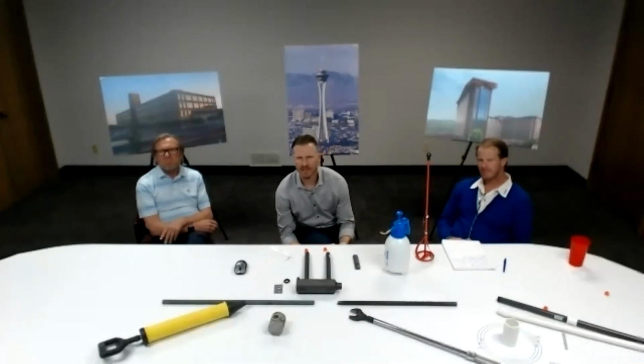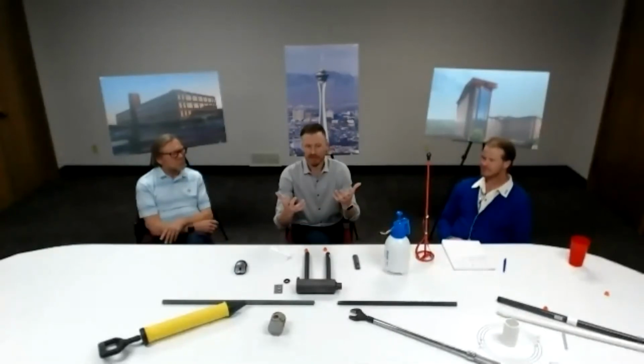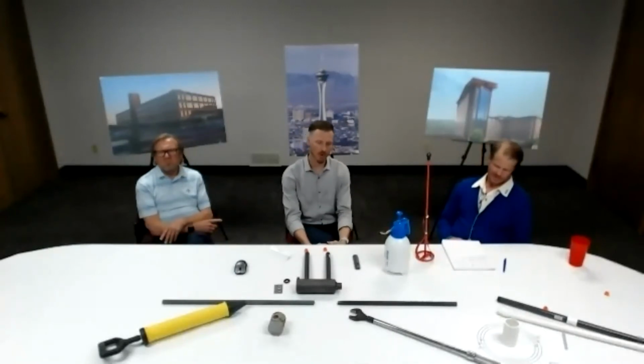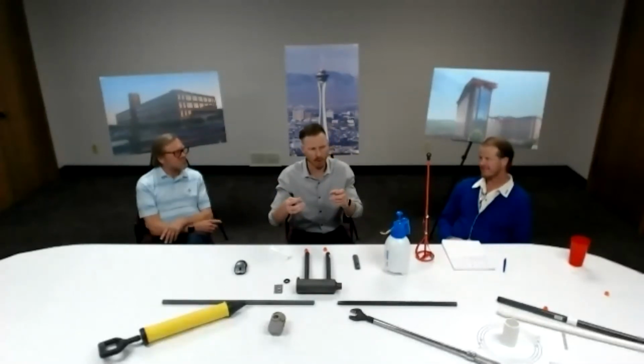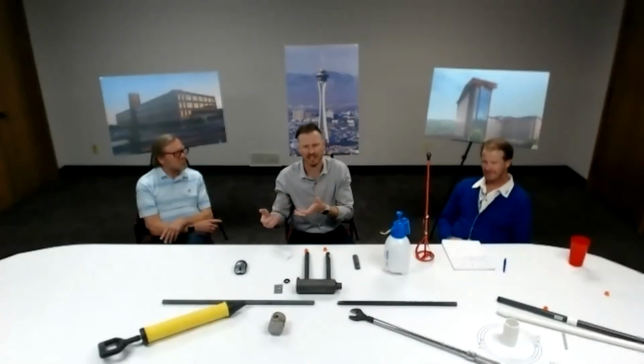A good question here about the PS0 being used in stadiums or on radiuses. We haven't done any stadium work yet with the PS0. I'm sure it's coming, but we did the Hard Rock. The project that the coupler was born out of, we took a bolted type coupler from the precast industry and were able to get that 8-foot wide pour strip down to about 1 foot.